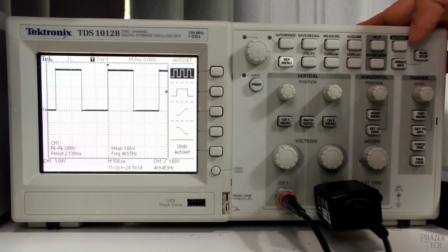Like I said, once you hit the auto set, and again, you want to make sure you are already outputting a signal before you push auto set, because it analyzes the signal to determine the best settings. If it's not picking up a signal and you push auto set, then it's probably going to change it to some weird settings. But let's go over some more details, because auto set might not always work. So it's good to understand some of the other settings in case you need to manually adjust it.